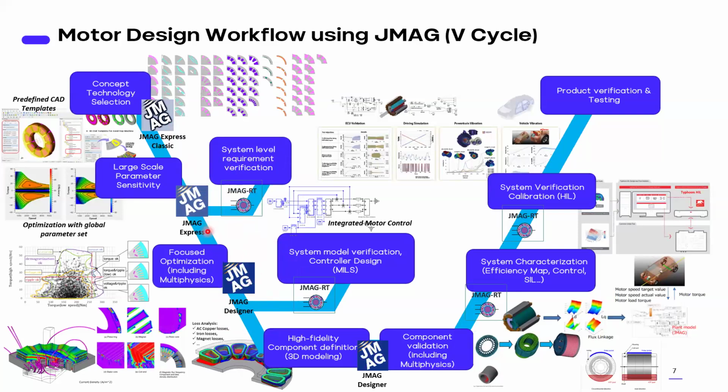So these are all system-in-loop simulations. Model-in-loop simulations include, once the electromagnetic simulation is done in the JMAG Designer part, the model can be taken directly into JMAG-RT and converted into a 1D model. And finally, it can be taken directly to the hardware-in-loop simulations.